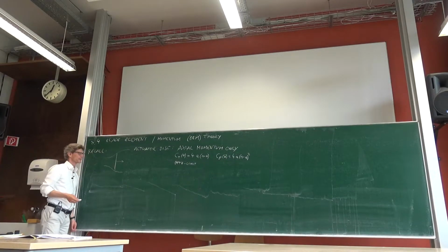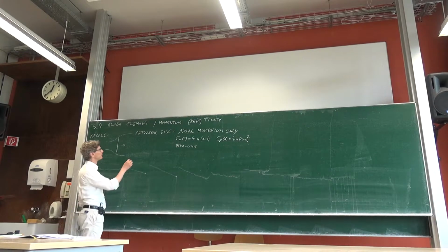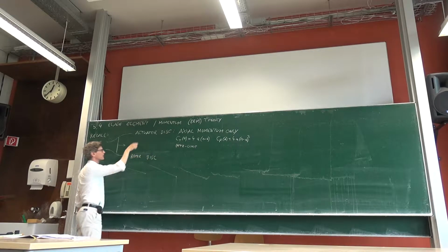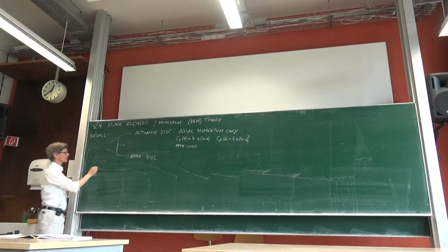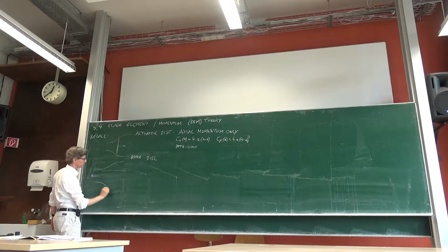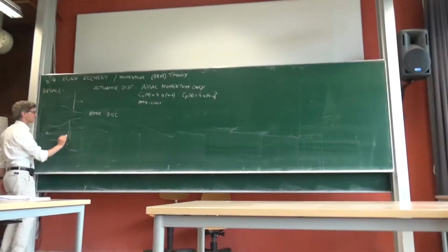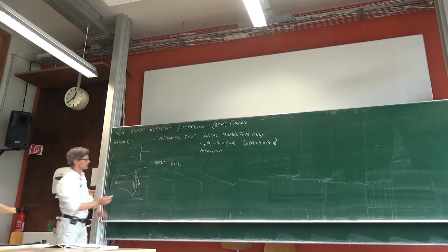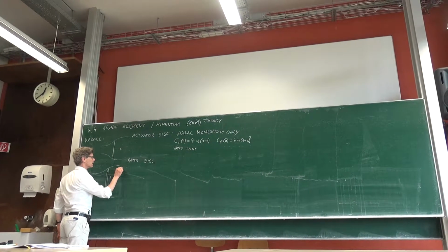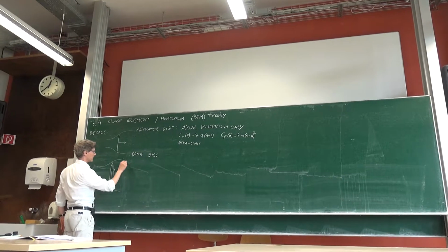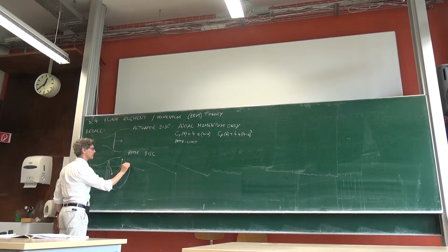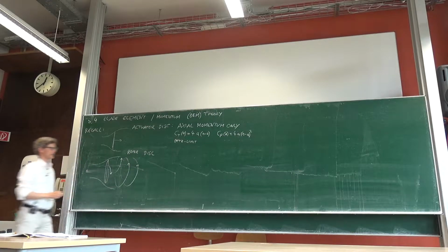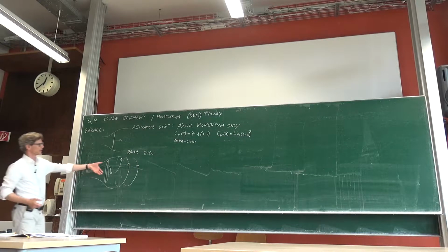And what we did then in the last lecture, 2 weeks ago, was that we were refining this to the rotor disk. So it's not just an actuator disk that just pushes, but it's now a rotor disk, and the rotor disk is, of course, still the same picture. There is a wind turbine, but this wind turbine is now, maybe I draw it in 3D, a rotating wind turbine, and it's pushed in this direction by the wind, and that means that the wind will be pushed in the other direction. So the wind is actually spiraling. Yeah, how do I draw it? Like this.